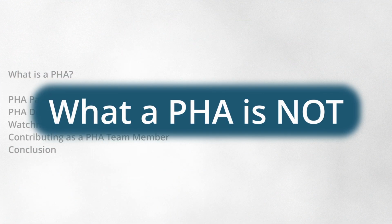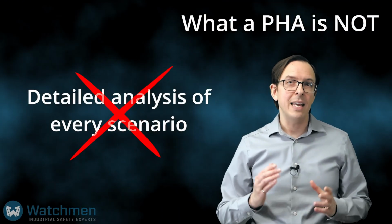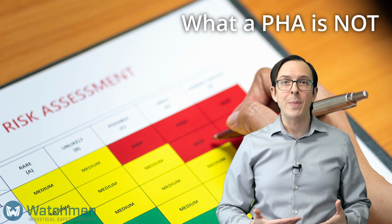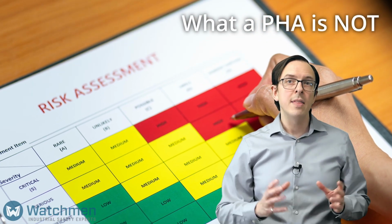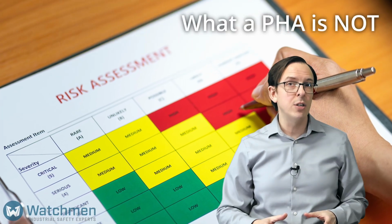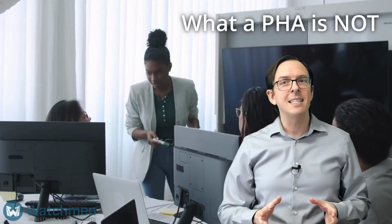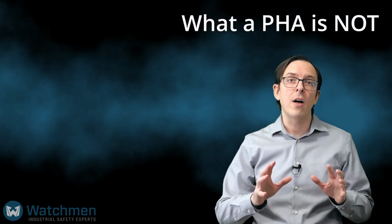What a PHA is not. PHAs are not a detailed analysis of each of the scenarios raised. Most PHAs will use an order of magnitude approach when assessing the likelihood and severity of a scenario. This means that there are only a few categories to choose from that each cover a wide range of values. This avoids the team having to spend too long debating those small details and focuses on the big picture.